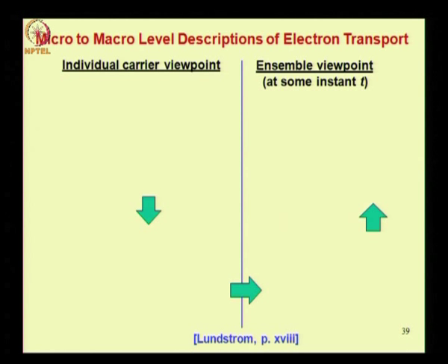we look at the device current in terms of the state of individual carriers, regarding them as waves. This approach in which we regard the carrier as a wave is valid when the device size or the mean free path between 2 collisions is less than the average de Broglie wavelength of an average thermal carrier.